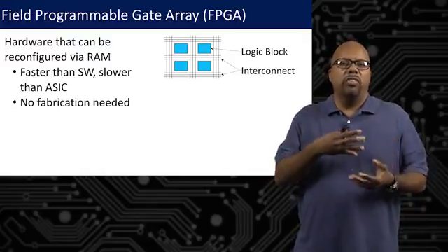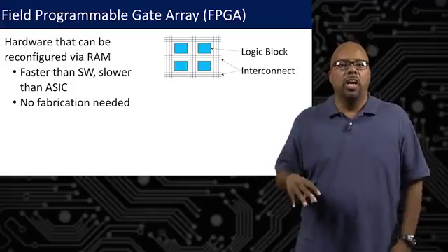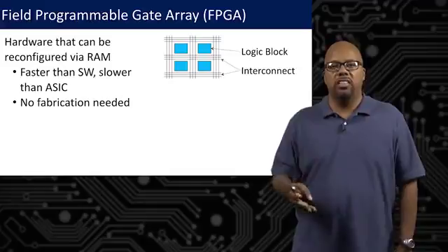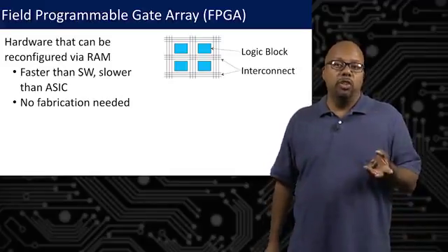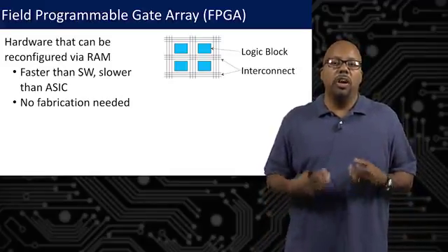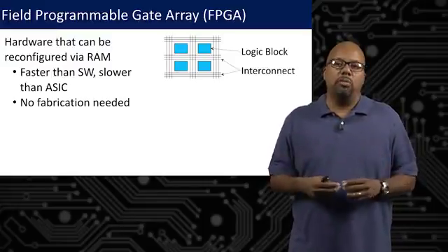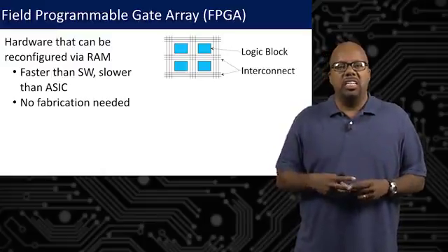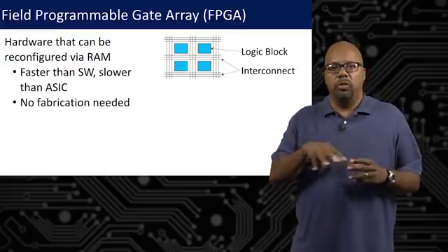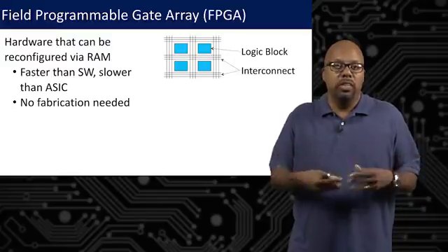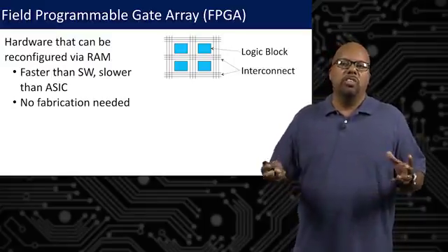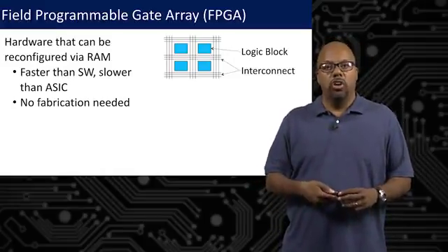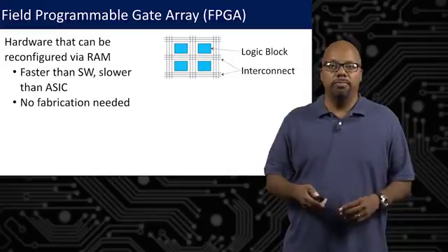Because there's a software conversion step that we won't talk about here that is skipped if you do it directly in hardware using an FPGA. So FPGAs have that advantage. And no fabrication is needed. See, when you make an IP core and you fabricate it as a chip, you have to manufacture chips, and that's expensive. So it only makes sense in high volume. With FPGAs, you don't have to fabricate. You just reconfigure it through programming. Just connect it by USB up to a computer, and you can rewire the thing. So that's much more convenient and cheaper. So if you have a one-off design, you would implement it in an FPGA over some sort of an IP core.